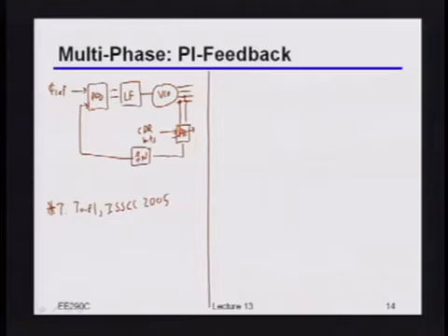Can you keep muxing between certain phases? Okay, you could do that. You could basically pick one phase on one clock cycle, and on the next pick a different phase. You could indeed do that, and that actually does work. Although that has the unfortunate characteristic that, because you're generating these big jumps, you then have to make the PLL sufficiently low bandwidth that it filters those jumps out, right? So you could do that, but unfortunately that has some not so good implications in terms of the PLL loop bandwidth. Yeah, go ahead.